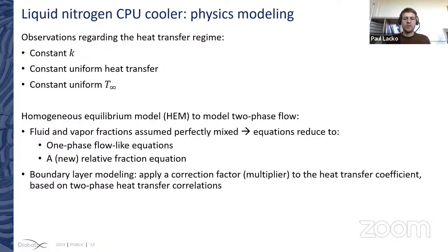Second, the heat transfer coefficient can be assumed to be approximately constant. Of course, there will be small variations within the pockets of boiling fluid, but these fluctuations are relatively small in comparison to the average heat transfer coefficient inherent to boiling. And third, since the phase change occurs at constant temperature, the far field temperature can also be assumed constant.